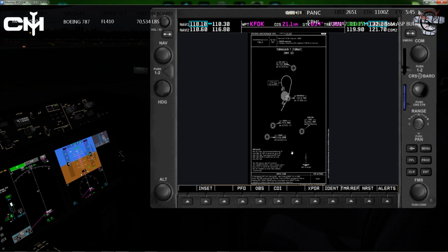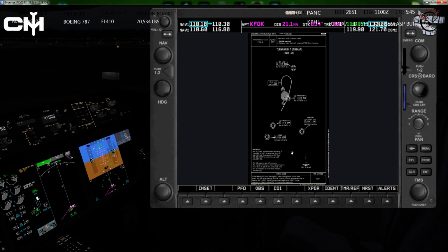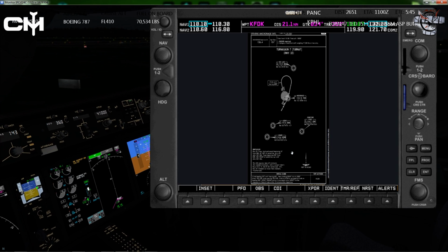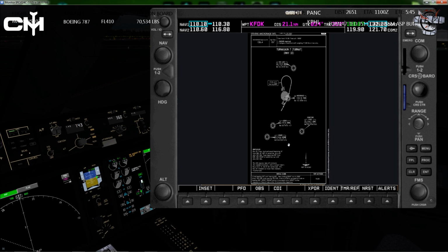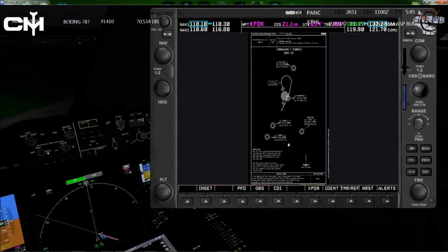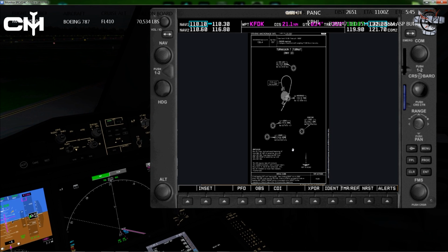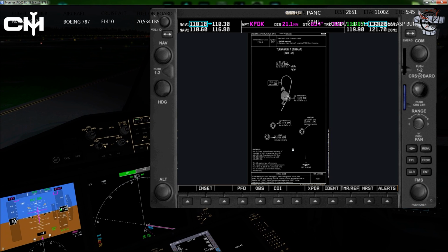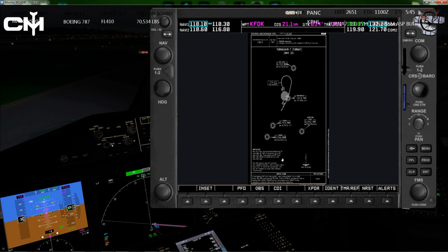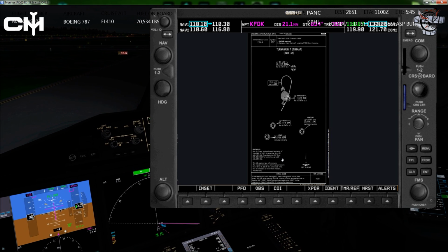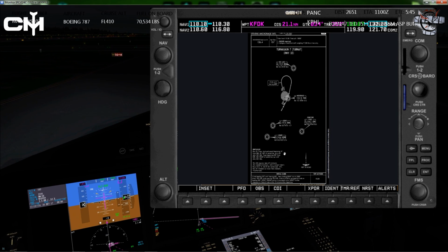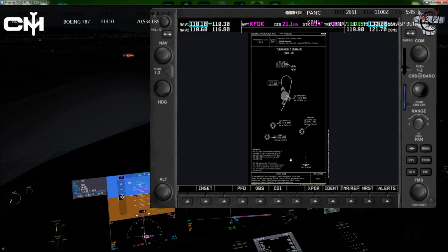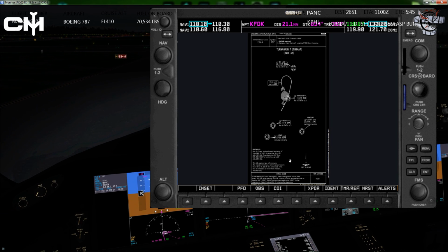You probably can't read that, but it says trees, bush, and nav aid beginning 10 feet from departure end of the runway, 85 feet left of center line, up to 60 feet AGL, or 182 feet MSL. Trees beginning 390 feet from departure end of the runway, 326 feet right of the center line, up to 60 feet AGL, 232 feet MSL. So just some departures basically. This SID does require takeoff minimums, on and on it goes.